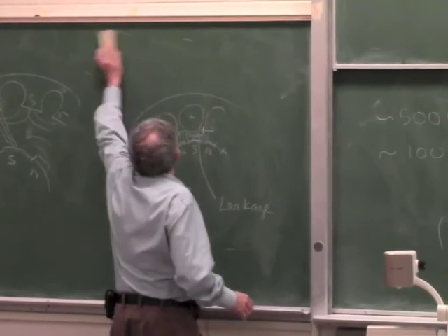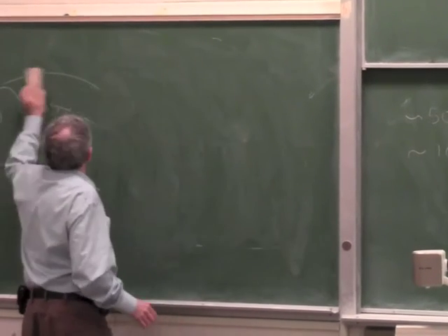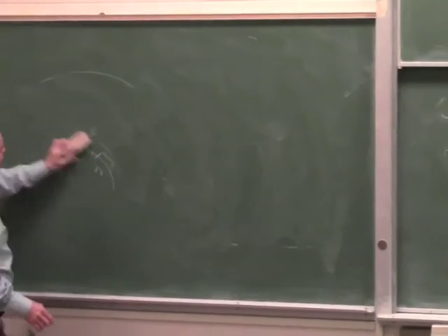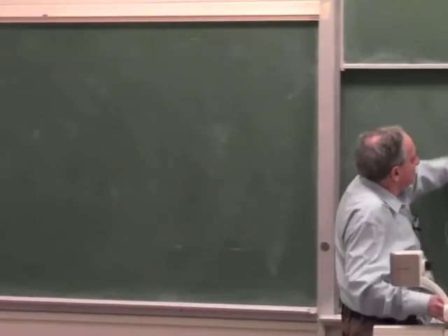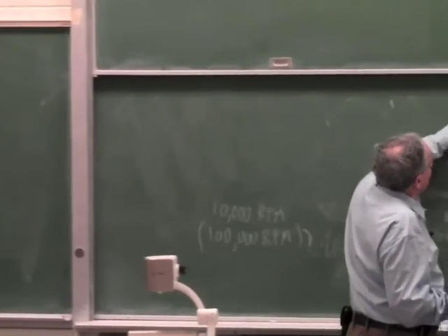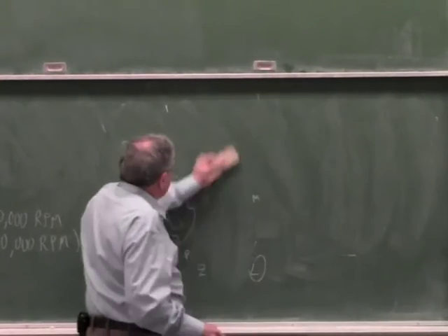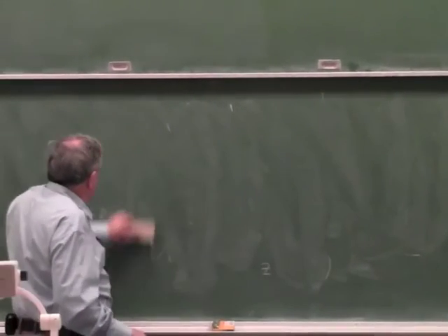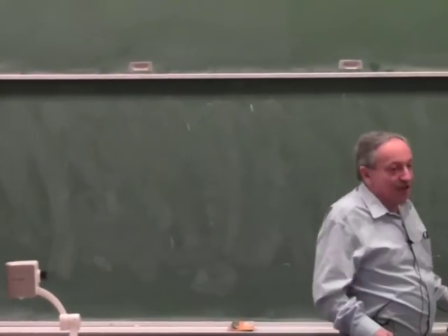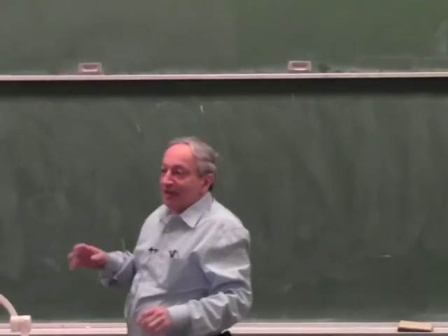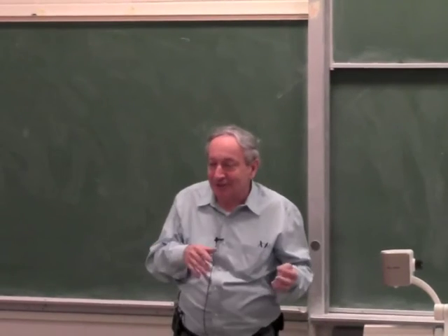Okay, so now we're going to the last subject on motors, and this is dynamic braking. As I said, dynamic braking is not so important in servos, because usually these are small motors. You are not so interested in conserving energy. But dynamic braking is very important in big motors for 2 reasons. The first reason, you want to conserve energy. Like if you have an electric car or even electric bicycles today, you want to recapture the energy going downhill.